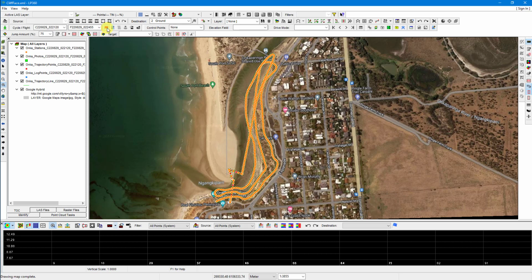So if you remember, we took our file from the base station and we sent it to AusPos, and AusPos gave us an accurate location for where the base station was. It then works out for us, off of that location using the Rinex files and the TO2 files, how much adjustment each and every location in the data set needs to go through. And this is right down to each point in the LiDAR point cloud.